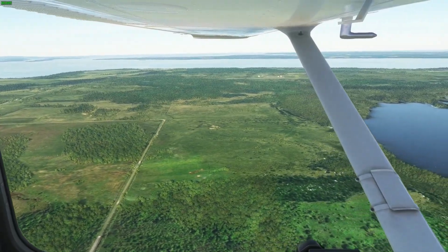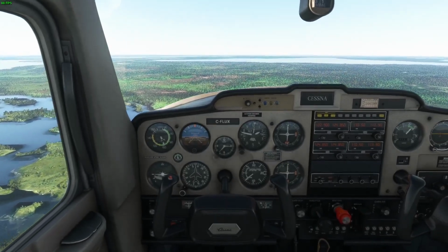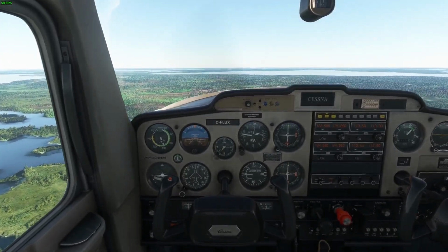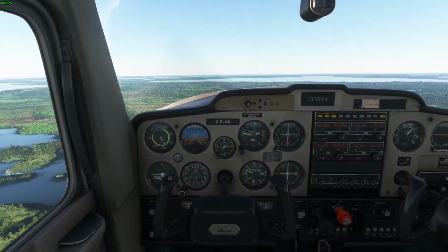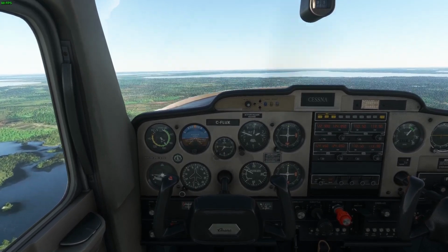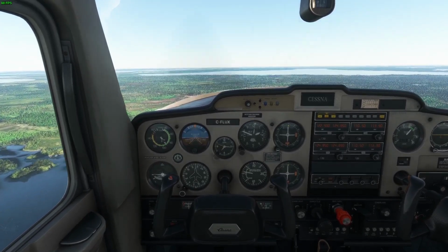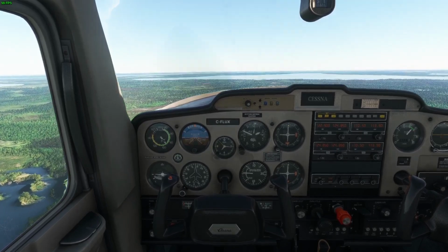Quick look, there's the airport parallel to us. Turtle Lake right under us there, it's a good reference. And pick a landmark straight ahead, the big opening of that bay. That is in the direction we want to go, so it's better to look at that. It's more accurate than looking at your gyro compass. Right? If you can see where you want to go, you just go there.